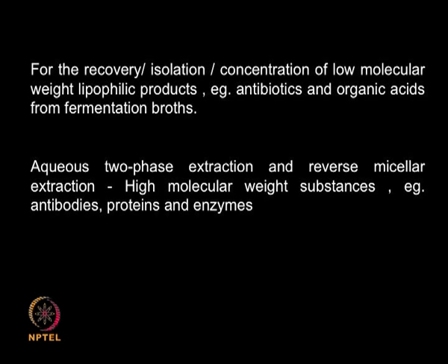So it is ideally used for low molecular weight lipophilic products like antibiotics, organic acids from fermentation broth, or I can use an aqueous two phase extraction system for even high molecular weight substances, antibodies, proteins, enzymes. So this technique is widely used for a large number of separation and purification downstream processes. It is a thermodynamic process, as I said, because there is an equilibrium between the streams that are leaving the stage.